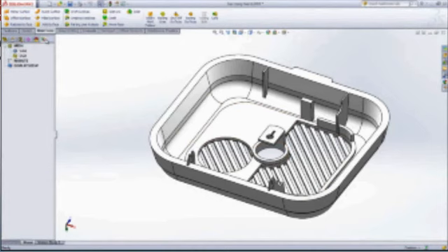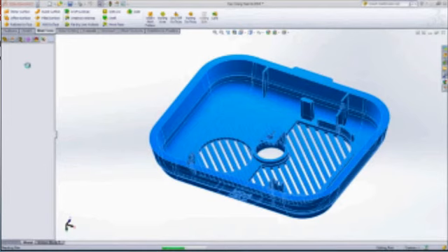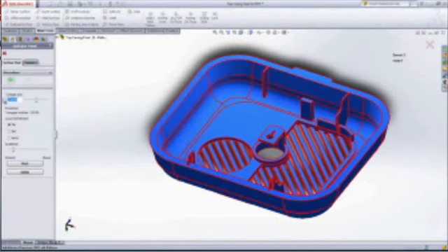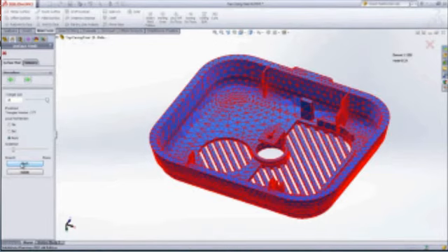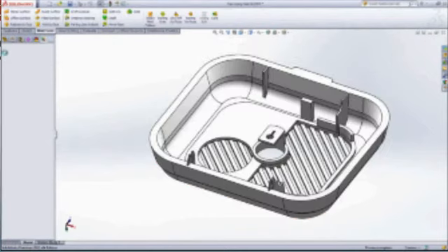After selecting the first configuration that we're going to look at, we can quickly and in just a few steps analyze the model. The first step, like other simulation tools, is to mesh the model. We can specify the meshing parameters manually or decide to let the software mesh this cavity automatically. Some parameters, like the triangle size for example, can be set up by entering a specific dimension or by using the slider. This helps to control the mesh density. We can also add some refinement to automatically use a smaller mesh for small features like ribs, holes, or higher curvature areas. You have complete control over the density and the quality of the final mesh.